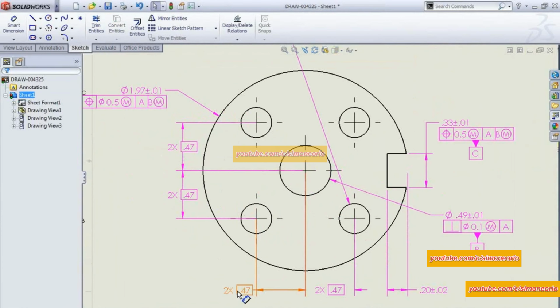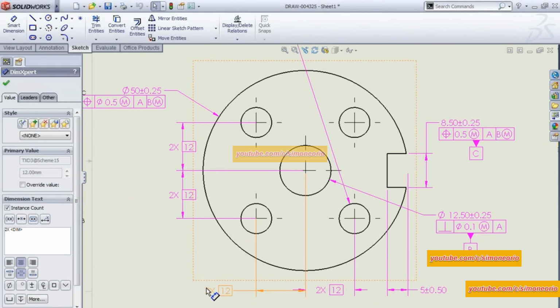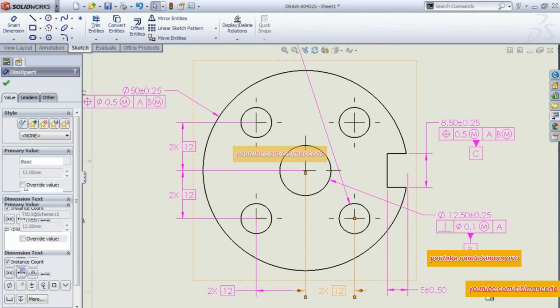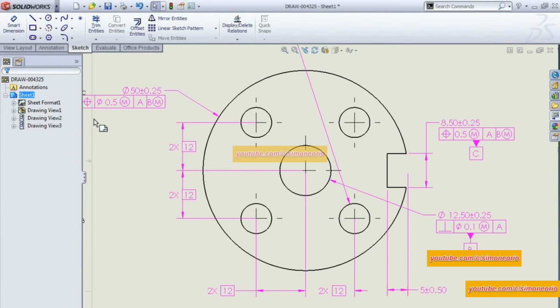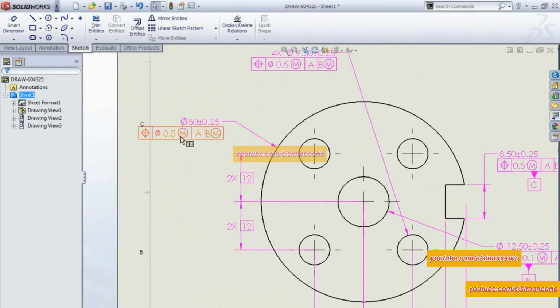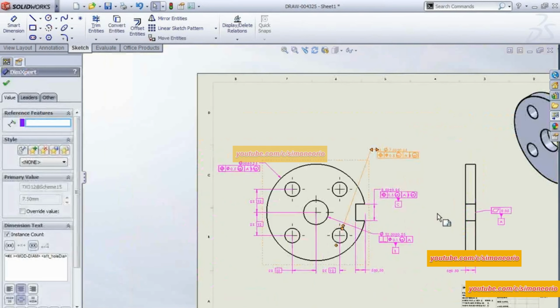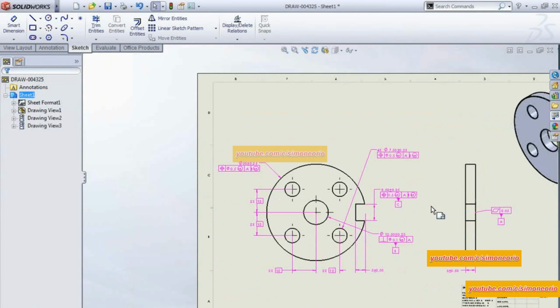And it does a fairly good job at spacing everything out. Of course, I want to make sure I'm in the same unit system, millimeters, for everything else right here. Not bad. Even gave it basic dimensions here, dimensioning to those features that have a true position tolerance. And you can position anything else you want as you see fit.